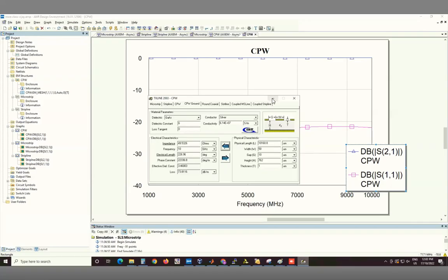So I have mentioned this casually, probably 2 lectures earlier. In that previous CPW, that difference between the TX line and the electromagnetic simulations, any ideas why the mismatch was so high? It was almost like 200 microns different on a 300 micron answer. So it said 300 and we had to go something like 500.